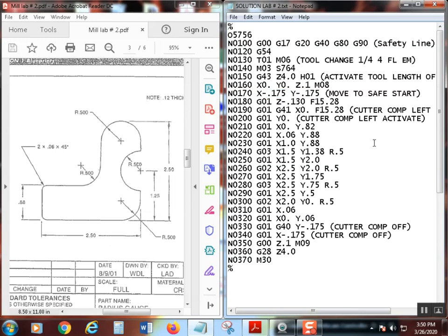Basically, if you had a half-inch cutter, 250 plus 50 extra thousandths, that's 300. So you'd set this at X minus 300, Y minus 300. If you do it like this, it'll work every single time. All right. There'll be other places we show you how to do other stuff, but this is not the most advanced class. So we're doing that. Remember, that is happening at a rapid move because that is modal. Modal means it's going to be that way until we change.